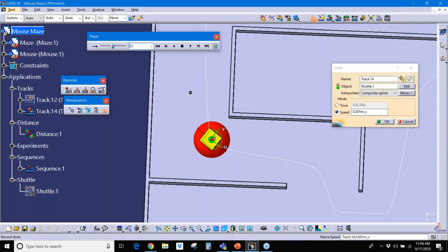So I'm going to say, okay, go to the shot, which is shot number 12, and then I'm going to kind of move this out, maybe like to here. And then there's a modify command. So y'all, hopefully everyone saw that the path kind of moved away from that a little bit. So by me physically moving the location of it over, I've then told it to have a little bit more space to kind of work around that. So that should fix my 1 millimeter clearance.